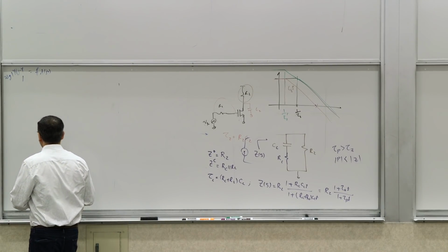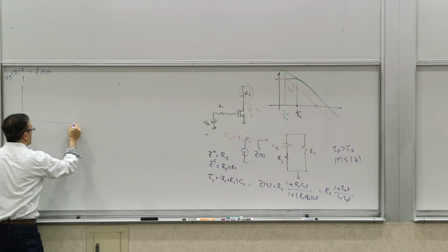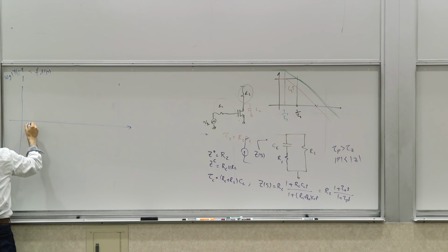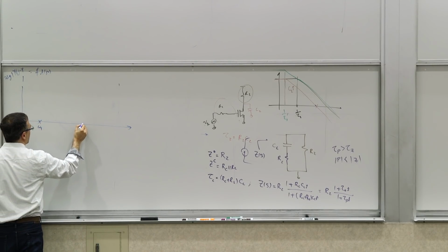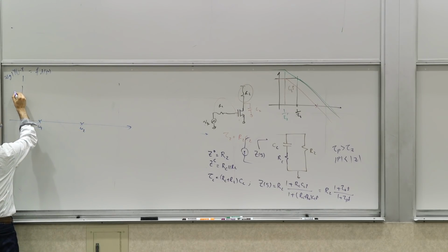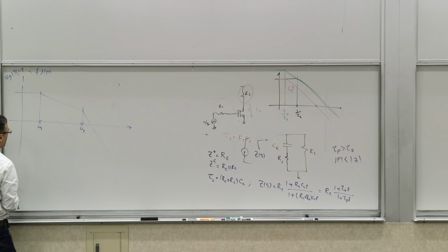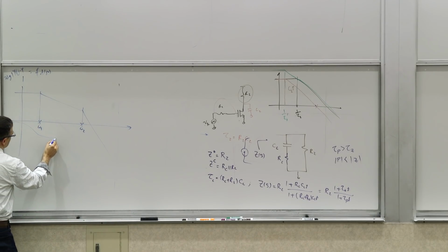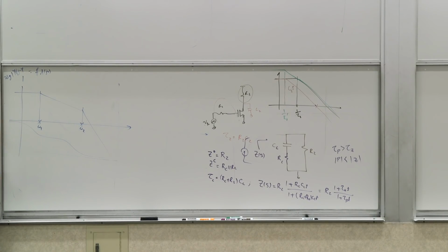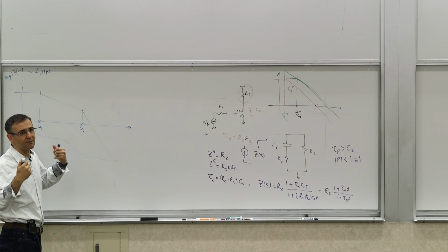And see what it looks like. So let's say you've got this system which you originally had an omega 1 and omega 2. And then you are starting here, you go there, and then you have obviously the phase. So you have two poles. And you're trying to make it so that you have a phase margin of, let's say, around 45 degrees or so.